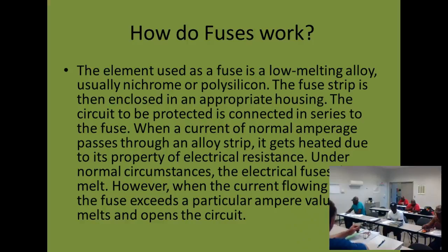I've seen guys' meters that read like 0.4 when they're touching. So you're going to, okay, your zero is at 0.4. It's like you kind of have to calibrate in your mind. That's as low as it's going to get, right? We hadn't put a path in there yet. It's got a perfect path, and that's as low as it gets.